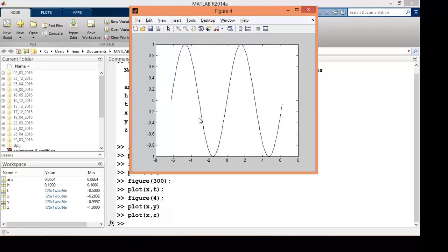If you do in MATLAB something like this, plot xy, and draw after this plot xz, MATLAB would in reality erase all the old figures in the current plot, and overwrite it with another new one. He will overwrite.